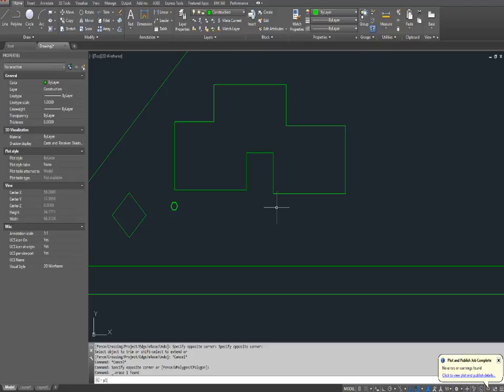Now you could go P-line and go from endpoint to intersection to intersection to intersection to intersection. And you could go through and you could draw this and go all the way around and make a closed polyline. Right? You can do that. But this is so much faster.